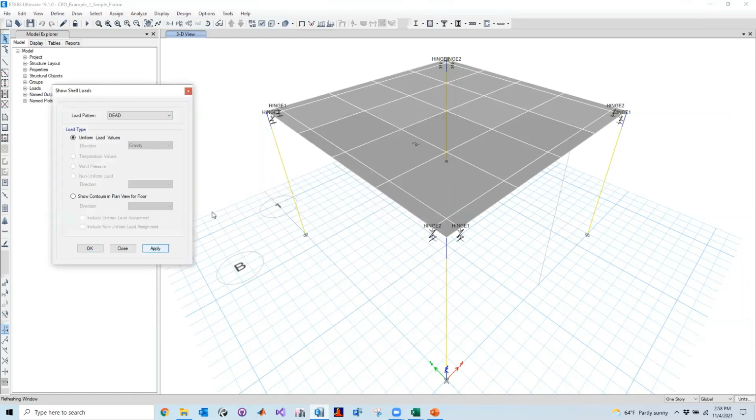In terms of the load, what we have over here, so I just applied, we're obviously going to use self weight of all the elements, and I applied just 150 pounds per square foot uniform load. That's the dead load. In terms of live load, there's no real live load here.